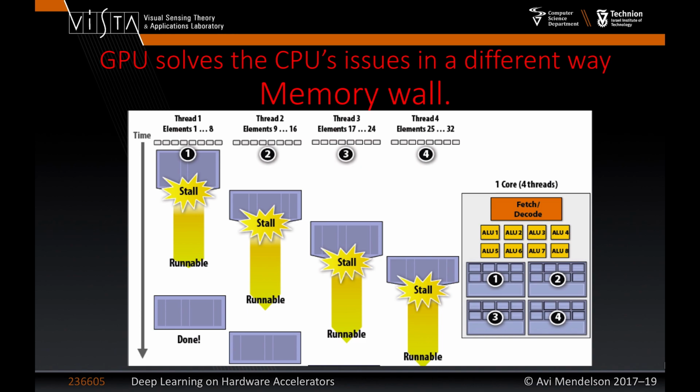And this architecture for sure trades the cache memory or memories with more data transfer to and from the memory, because if you have many parallel architectures, you need to read and write them all the time. You have small caches, so you have more traffic to the memory. And apparently recently people showed that the major impact of wasting power is memory transfers and not the ALU anymore.